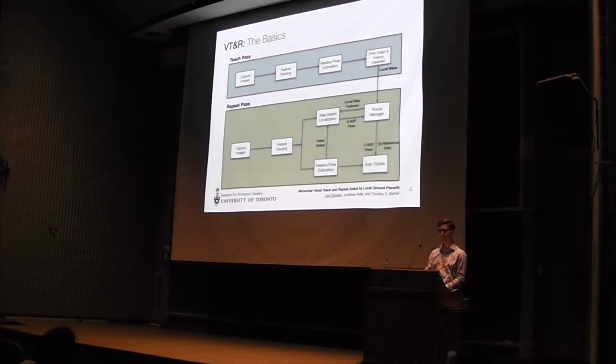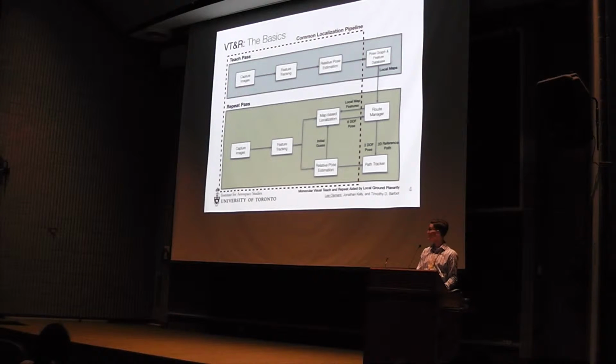So you can project your 6-degree-of-freedom pose from that procedure down onto some local ground plane and do path tracking against it. The path tracker that we use actually controls for two things: the heading error, which is which direction you're pointing along the path, and also the lateral path tracking error, which is how far off perpendicularly you are from the route.